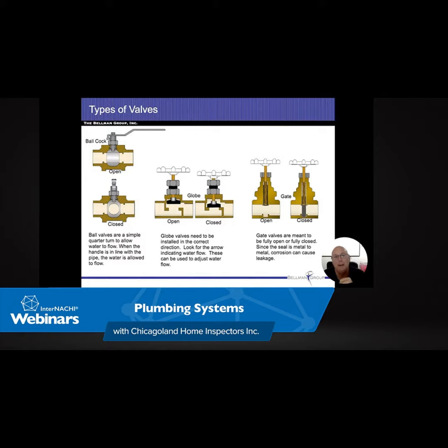All right. Residual pressure is the amount of pressure that's left in the water system after the water is flowing. So what we're showing on this slide here is on the left-hand side, we have 60 psi coming into the water system. And where it's discharging with the water flowing, we're left with 24 psi. What they're trying to say in this slide is it doesn't matter the order of flow. If I go big pipe, little pipe, big pipe, none of that matters. It all totals out and equals out wherever it is at the final run, and that's going to be our friction loss. I want you to remember the term residual pressure and static pressure.